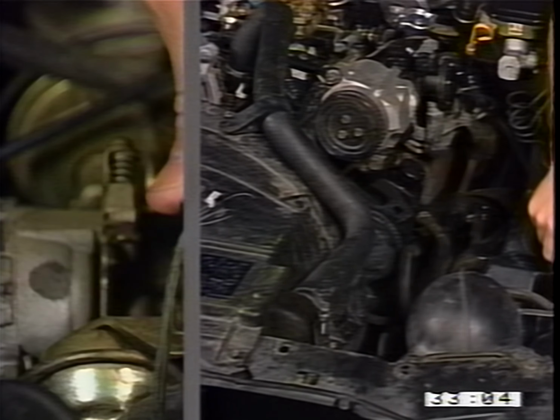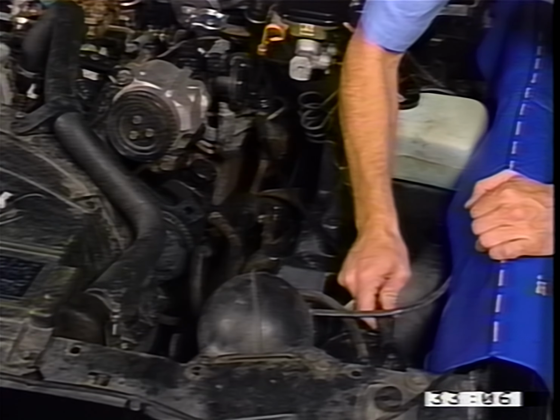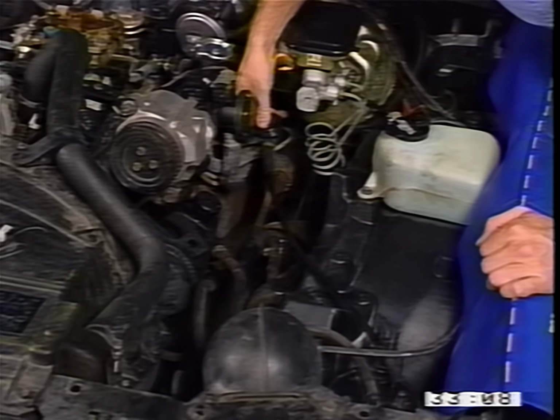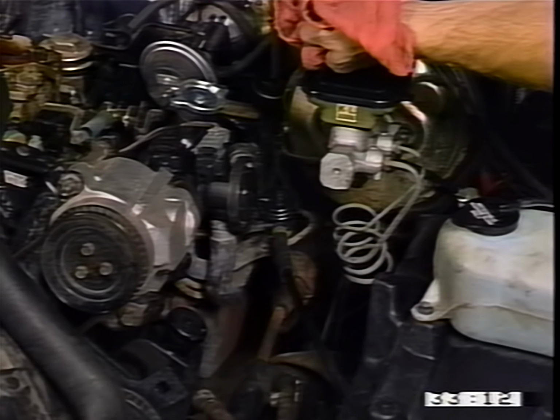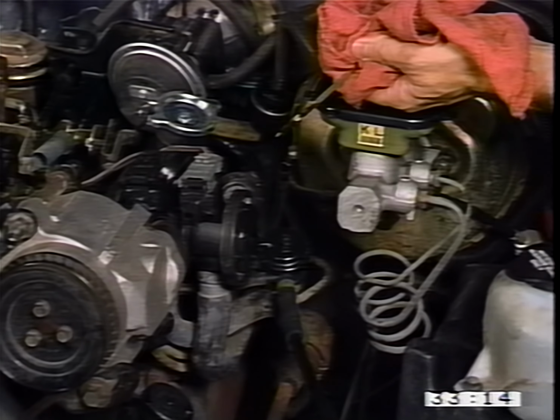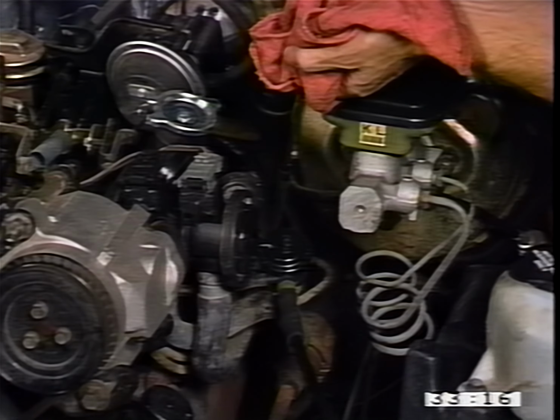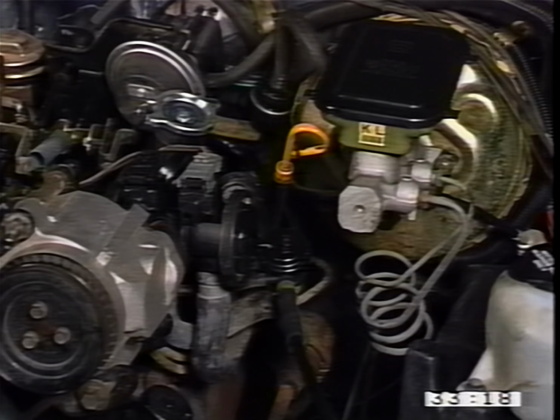The evaporator and canister are then checked for fuel loading. Purge valves, bowl vents, and fuel in the crankcase are checked out as possible causes of RPM drop or increase. If these check out okay, then the carburetor or MC solenoid is probably at fault.